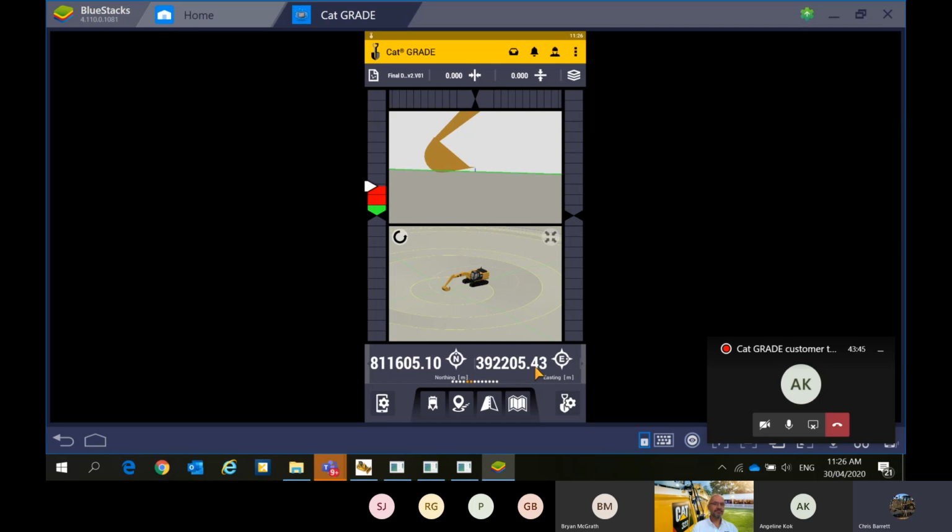Well, first things first, and this is one thing we really strongly recommend: before you go digging too far, to keep that cranky foreman off your back, go check this machine on a known survey point. When the job's done, there's a control point there that's going to have a northing, easting, and elevation value. And again, using that text ribbon we just set up, we can go across looking at the elevation and the easting. So this verifies quite a few things.